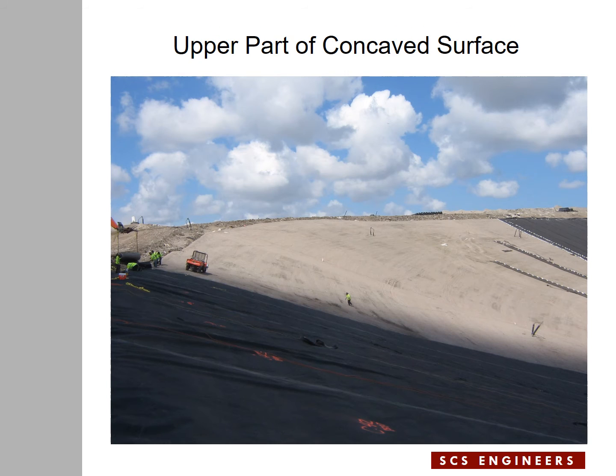Here it shows the upper part of the concave surface. The soil has been graded properly and is ready to receive geomembrane, and the geomembrane panels are going to be installed in a certain way that is up to the superintendent of the installation crew.